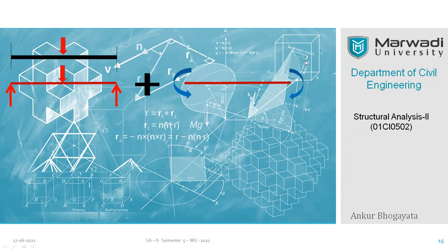That you have to remember, right? It will be nothing more than a rectangle. The only thing is it changes when you have continuous beams, because on one end you have a fixed end moment with x value, but in the next level, if you have another beam available over here, and if it's having different span, then definitely the fixed end moment will be different. But that is a complex or next level example, so don't worry about it.